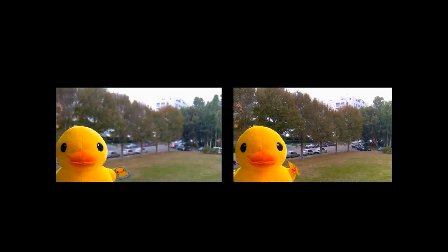Well, you can see in the image here to the left, the pumpkin in the front of the image is in sharp focus, but the WiseNet 3 sign in the back as well as the subject in the background are both out of focus. This is because scenes with varying light, with light coming from the outside in, cause the camera not to be able to focus on the whole scene because it has what's called auto iris or conventional iris. But if you had the same exact scene with a camera that has precise iris or PIris,